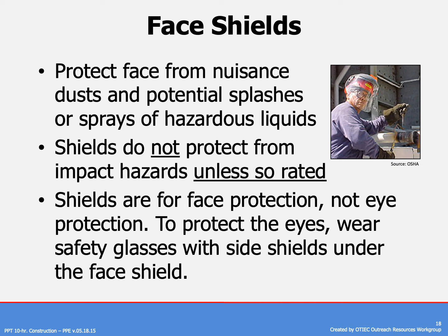Shields are primarily for face protection, not eye protection. So if you're around something chipping, grinding, welding, you want to wear safety glasses underneath that face shield as well. If you're working with corrosives or caustics, something that could splash, you may want to have goggles underneath that face shield as well, just in case something were to splash underneath that face shield itself.